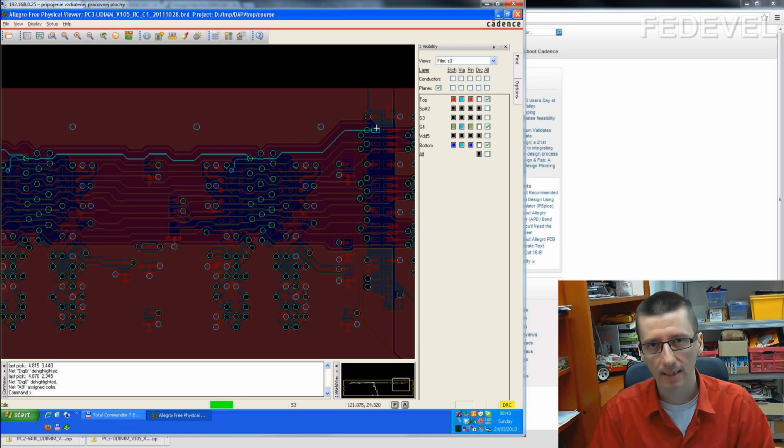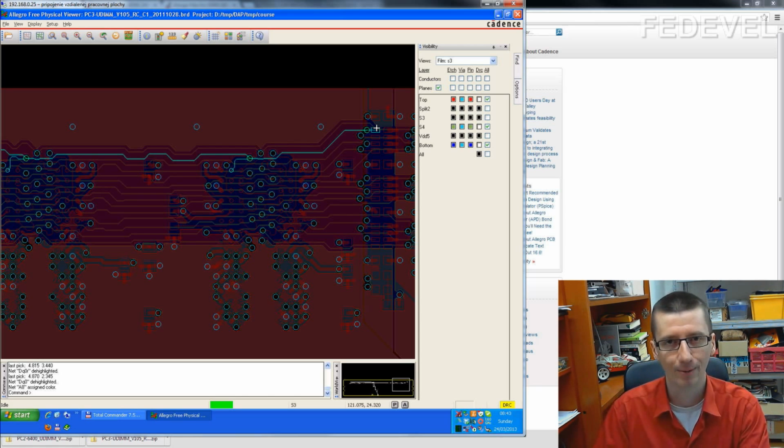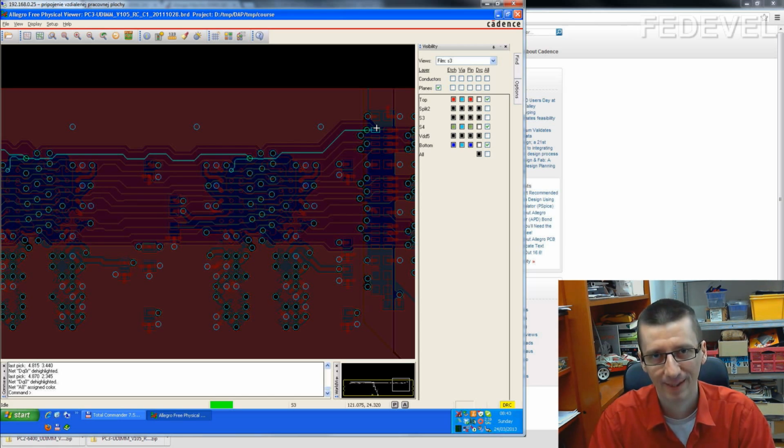Why read design guides? Because I was doing one DDR3 design, which specifically said use T-branch topology. So be very careful. Now you know what the difference is between DDR2 and DDR3 layout, and we can go back to our hard work.